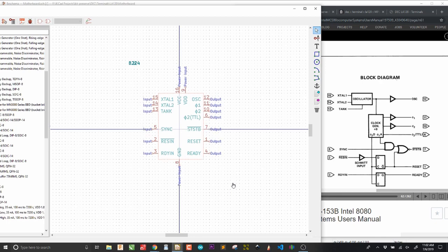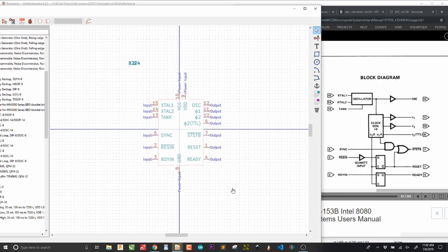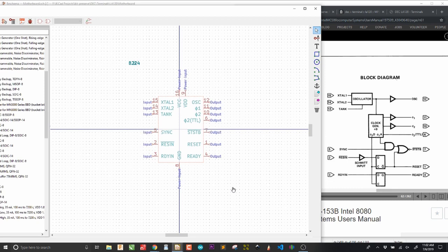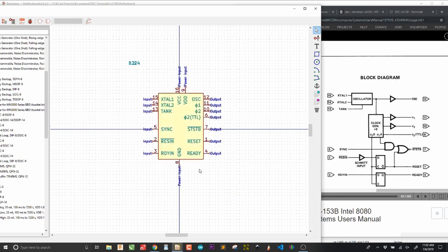So again, you want these roughly so that the chip is centered. Now this would be the chip centered, but of course then the pins are not on the correct grid. So I'm just going to bump it up 1. And we can see that this side is longer than this side. So I can probably fix that by moving this out by 1 and hitting G to grab the end of